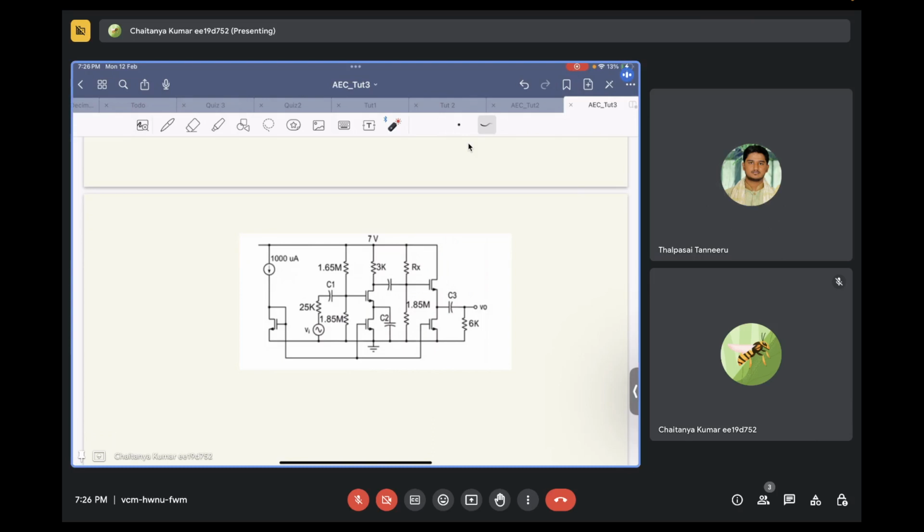No, where is the cascode? Yes, there is no cascode, only cascade. Cascode happens when there is a transistor above the input transistor. Let's say there is a cascode for this transistor, but that does not matter at all, because this is anyways going to get shorted in small signal.